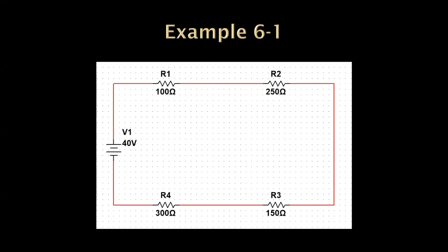which one is going to have the highest voltage drop? Which resistor will have the highest voltage drop? R4, right. Okay, highest resistance, I'm going to have the highest voltage drop there. It's going to take the most force, the most voltage to get through that resistor. So which one's going to have the lowest voltage drop? R1.